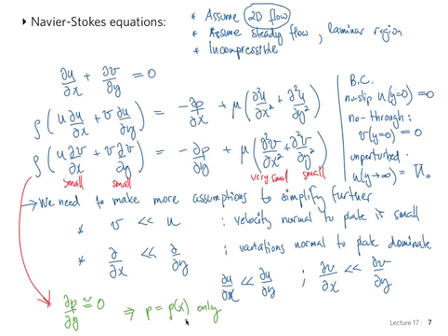Bernoulli's equation. I can do Bernoulli's equation in the inviscid area, in the area where there's no viscosity, and so the pressure is going to be known. Basically, the pressure completely drops out of the whole discussion from now on. Does that make sense? It varies only in the x direction. In the y direction, we can assume it to be a constant. Somewhere in the y direction, the fluid is unperturbed and inviscid. So the pressure there is known by Bernoulli's equation. So it's known everywhere.